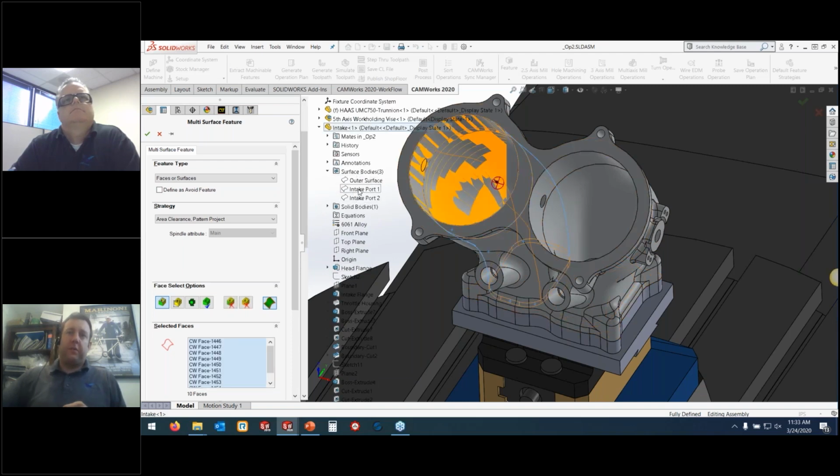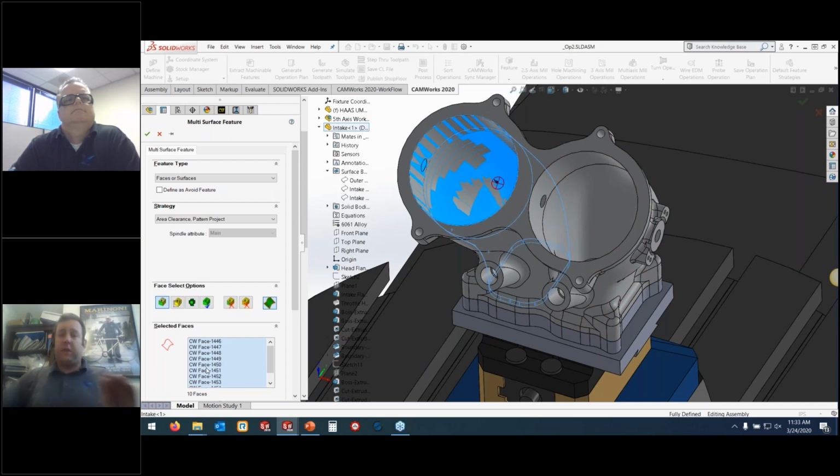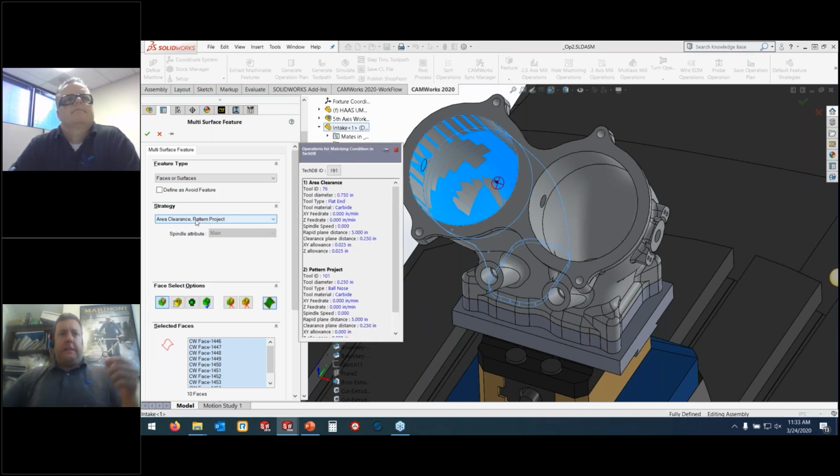So we're going to use that on the surfaces, and just clicking on the surface itself means I go in and select all those faces in the tree here. I don't have to mess around clicking on every single little face. That gets boring. I hated that when I used to do those little polylines and I had to click every single little line. Hated it. So I'm just selecting the surfaces here in one click.